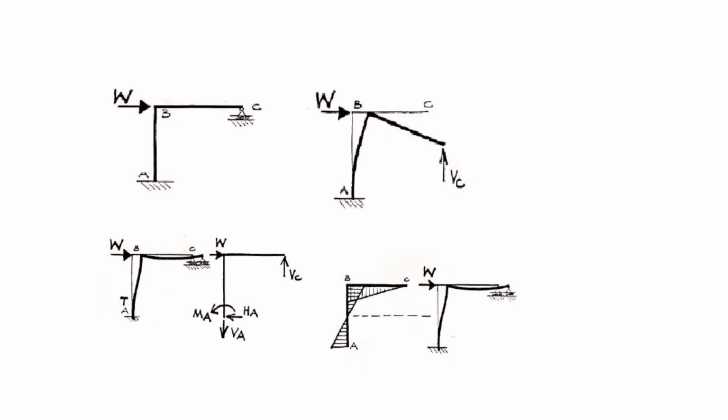Here we have this support, right? Here we have tension on this side, and the bottom side is fully in tension. That's why, if tension comes on the bottom side, we draw the minimum diagram on the tension side. Because of this horizontal load, point B moves here and C will be moving downward, and horizontally it goes up. When it goes up, we need to maintain the right angle at B, so it will bend like this, and then here we have the support, so it will bend like this, right? This is how the minimum diagram comes.